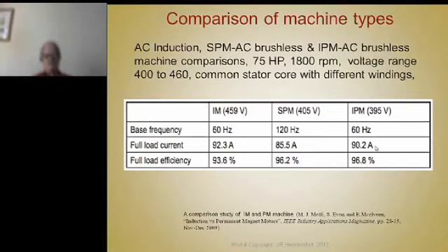the salient poles, and that was done effectively by using power to saturate part of the magnetic circuit around the poles, around the magnet poles, to force the torque through the saliency part of the poles. So that's kind of effectively equivalent to, since you had to magnetize that part of the circuit for the reluctance torque component, it's almost the same current as what was required to magnetize the current for the induction machine.